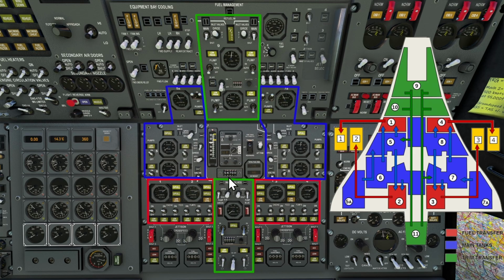For departure, the center of gravity, which is indicated here in the middle, needs to be at 54%, which it is right now. But in our supersonic flight envelope, we need to pump fuel back. We cannot trim Concorde with trim surfaces like we would do in every other aircraft. The drag is just too high, the speeds are too high. So we have to trim Concorde with the fuel. And we have to pump fuel from the front to the back to get the center of gravity also to the back of the plane at 59%.